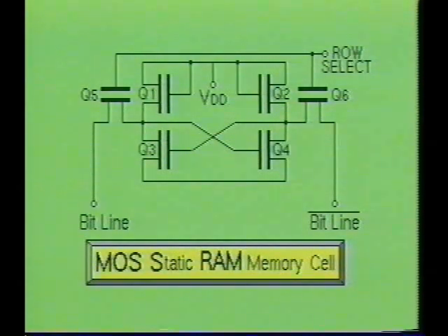Since static RAM uses flip-flops to store each bit of information, and each flip-flop requires the use of 6 transistors to store a single data bit, there are design limits to the number of reliable transistors which can be manufactured on an IC chip. Also, as the static RAM gains size, the power consumption begins to grow, and the heat generated within the device will begin to affect the operation of the circuit.